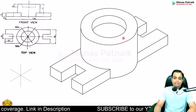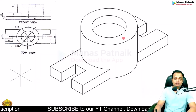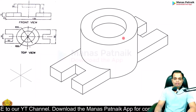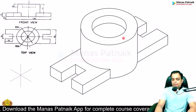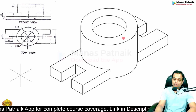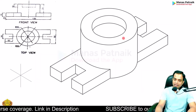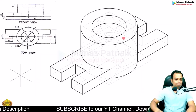Use an edge pencil for the final touch up. And if you want to see the construction, some teachers get annoyed if you erase all the construction. Don't do that. Keep the construction alive. Make sure your construction work is very, very light. Use a very light sort of grayish pencil. A 3H pencil will do the job for you. If 3H is dark, then go for 4H. Your choice. Different companies have different levels of darkness, so that is the problem you have to deal with, but you can work it out. Light means light, dark means dark, and your construction along with the isometric is like this.